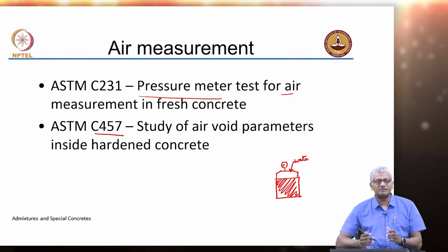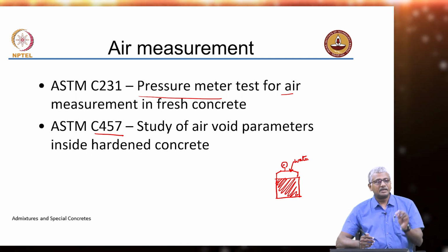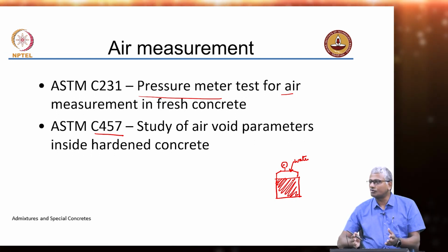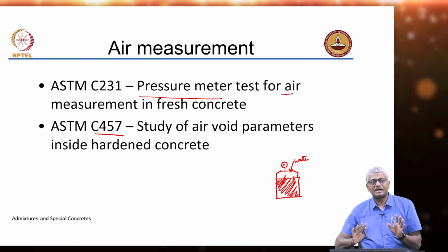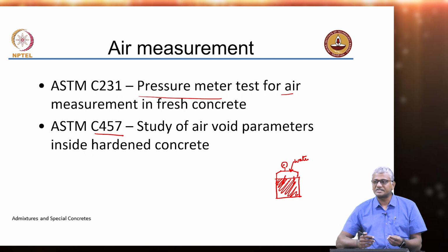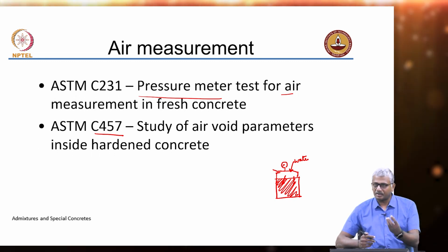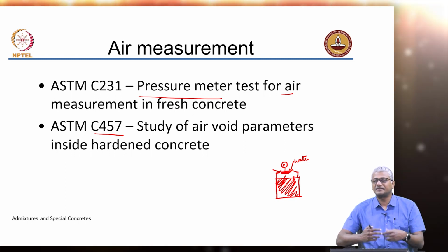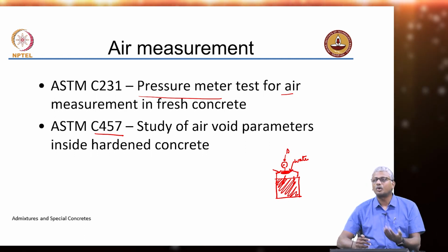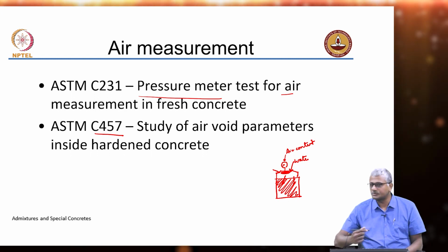Even if you take a concrete structure which is 50, 60 years old, and take a small microscopic image from inside, you will find that much of the C4AF is present as it is in the original cement. It is not reacted at all. That is because iron is present and this iron makes it highly insoluble. Cement particles have to first start solubilizing and then they react. So, C4AF is a phase that does not solubilize easily. As a result, you will not find the C4AF phases having reacted much even in concrete that is very old.